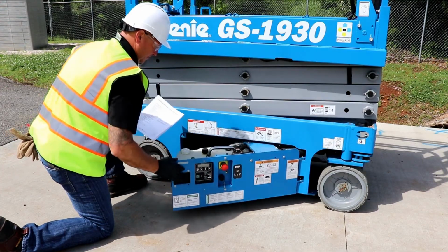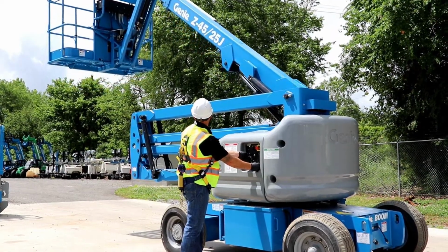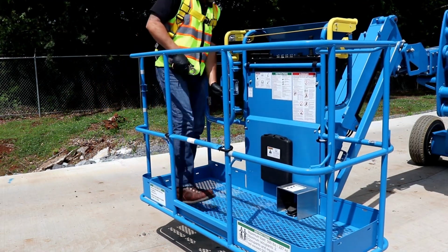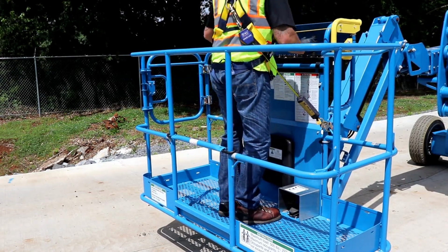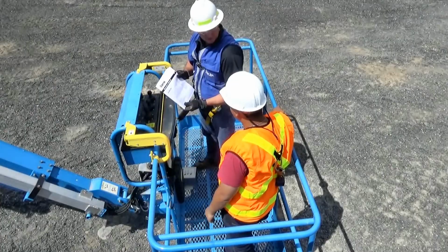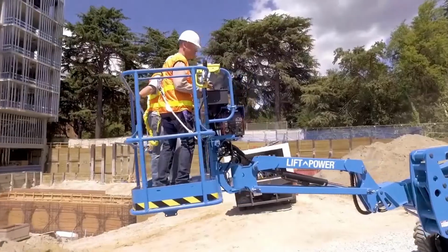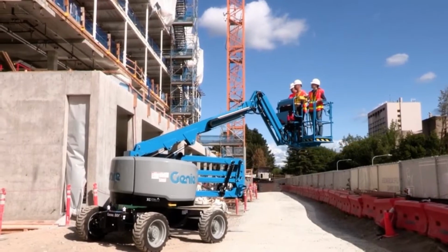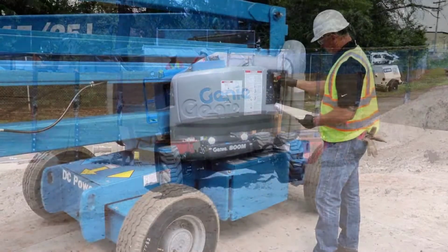This includes avoiding hazardous situations, performing a visual pre-operation inspection, performing comprehensive function tests prior to use, performing a workplace inspection, and only using the machine as the manufacturer intended. The operator is responsible for reporting any problems or malfunctions that occur before or during operation. And finally, the operator must ensure that all occupants in the platform have a basic level of knowledge to work safely on the MEWP. In addition to these important standards, operators are subject to specific local, regional, and national workplace rules and regulations, so please check with the appropriate safety organizations for specific information that would apply to you.